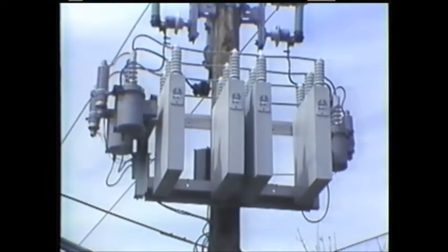Capacitors are very easy to recognize because they are square or rectangular in shape. The number of bushings on top of the capacitor may vary. These are three-phase capacitors. In most cases, you'll find capacitors connected together in banks. Here, individual capacitors are connected together to meet the load requirements of a specific service area. The ability of a capacitor to counteract reactive power does a great deal to improve the overall efficiency of a distribution system. A capacitor's ability to store a charge, however, can present a considerable safety hazard to you and other T&D personnel.